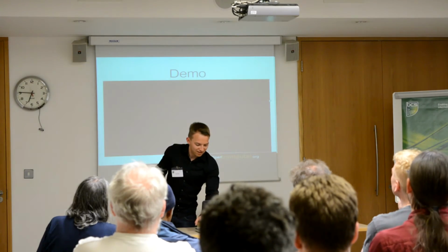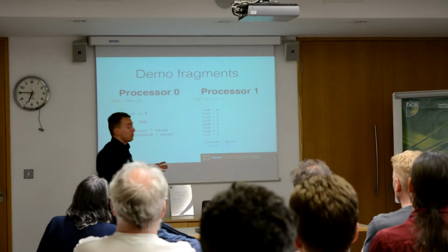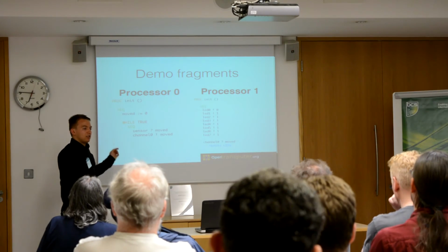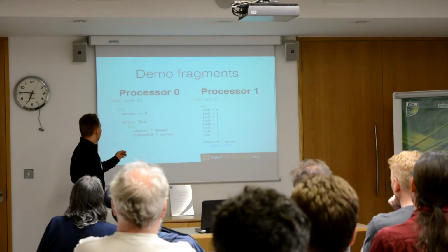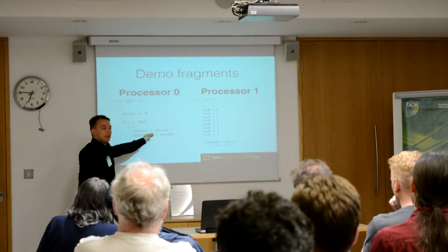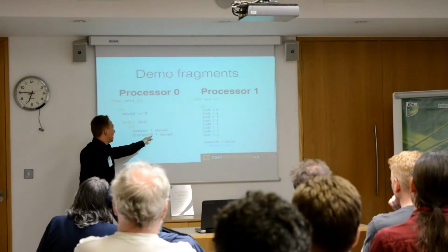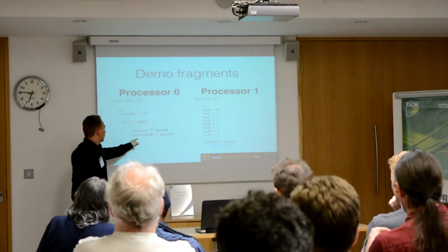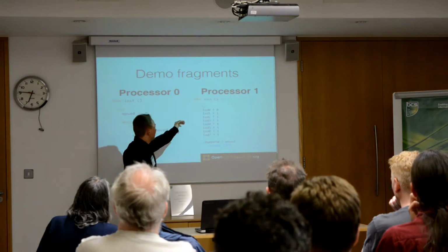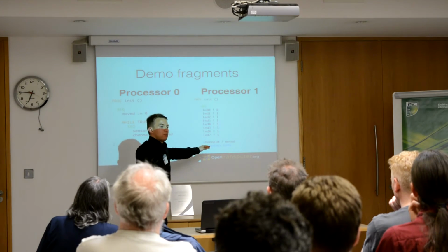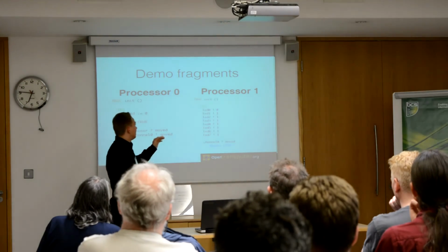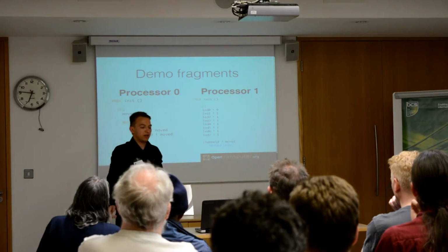This is the code we used to run the demo. On the processor that is connected to the proximity sensor, we simply receive a value from a channel into the flag moved, and then we send this flag through channel 0 to the other processor. The other processor is connected to 8 LEDs, and depending on the value of the moved flag, the LEDs are updated to flash in a certain pattern.